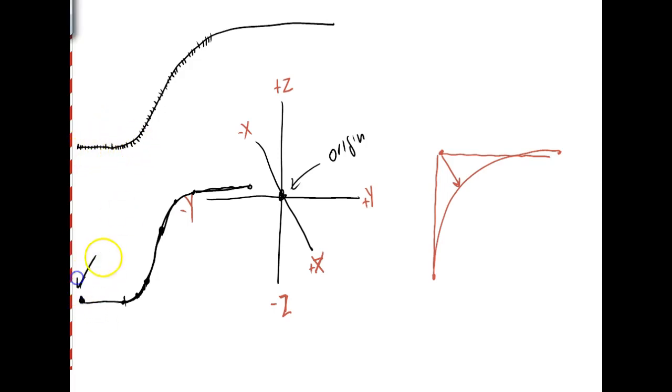Here I have to do what? I have to jog it to these points. Up here I do what? On a continuous path robot, I literally grab the robot and I move it through the path that I want it to follow. And then what happens is the controller has what they call a sample rate, where it just saves 1,000 points. And here you don't have to do round off or anything because these points are so close together that it would make it smooth. That makes sense?